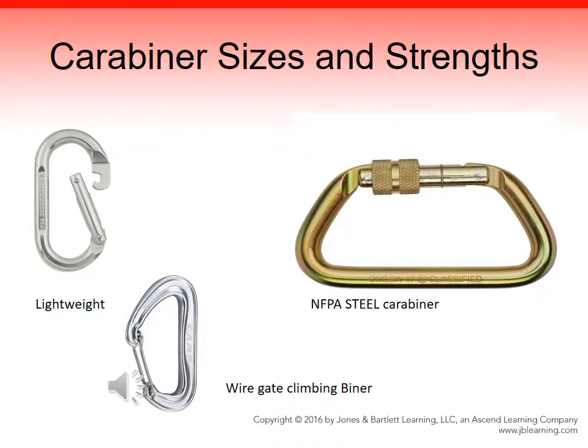Because climbers must carry their equipment with them, carabiners made primarily for rock climbers tend to be lightweight. Some are constructed of hollow aluminum. They have low strength ratings, and carabiners need higher strength ratings for more demanding use. Higher strength is essential for when more than one person's body weight may be involved, such as in rescue situations. Such types are made of solid aluminum or steel.